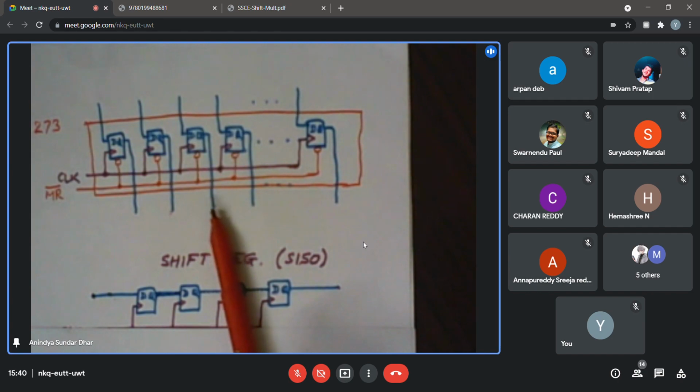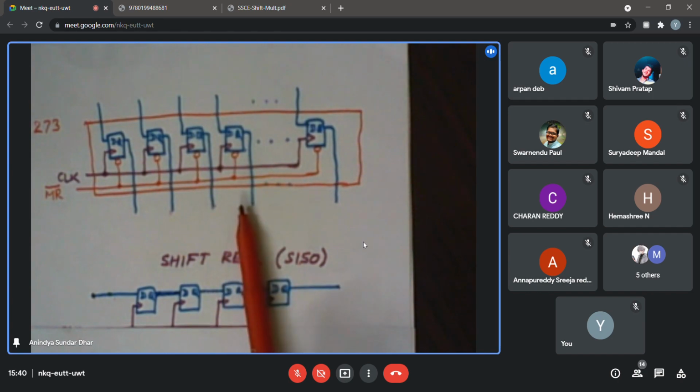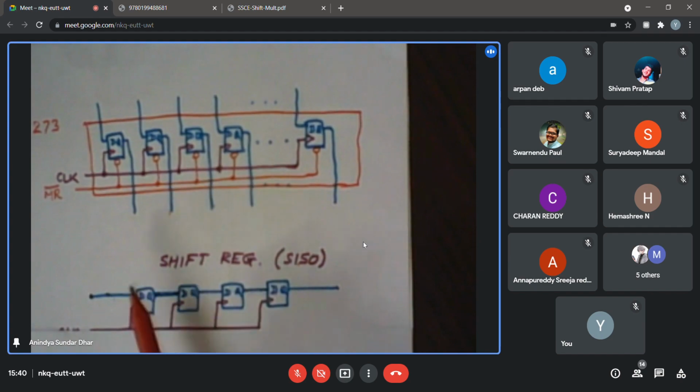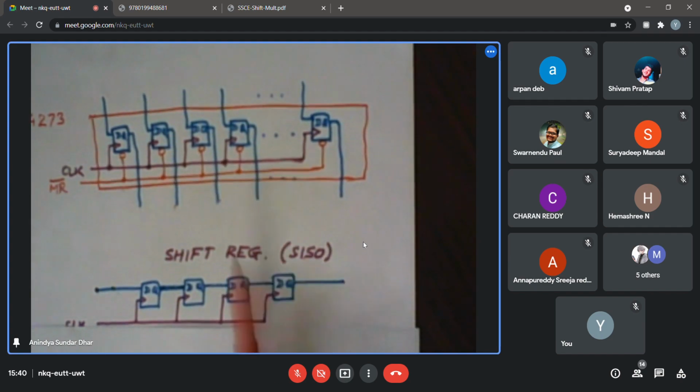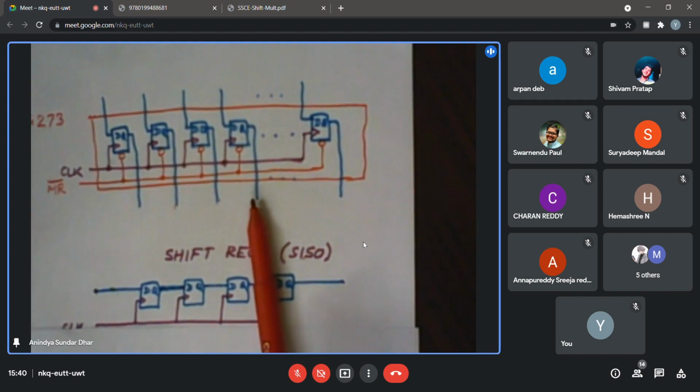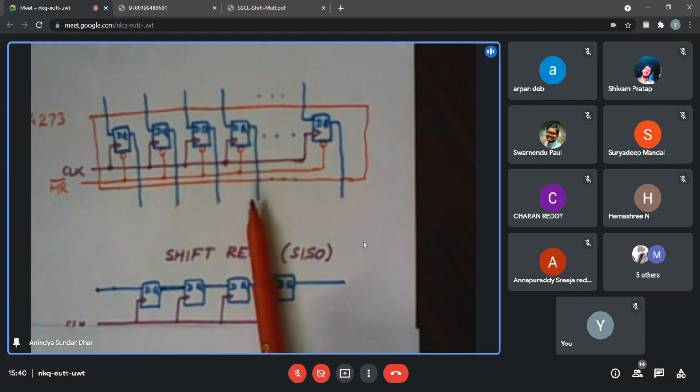Okay. So if you remember this statement, basically there are 2 sentences I said: that some portion can be converted into a shift register, and you need not convert the whole of it to a shift register. You can break it up into 4 or 3, 5 bits, whatever, and then use some portion as parallel in, parallel out, and some portion as serial in, serial out. So probably that will give you enough hint.